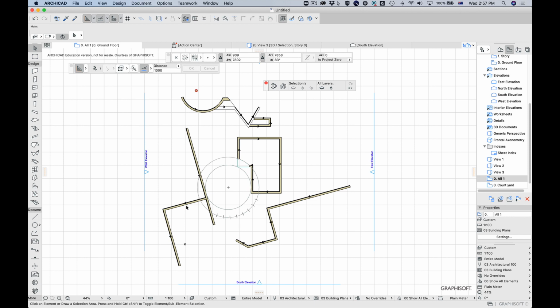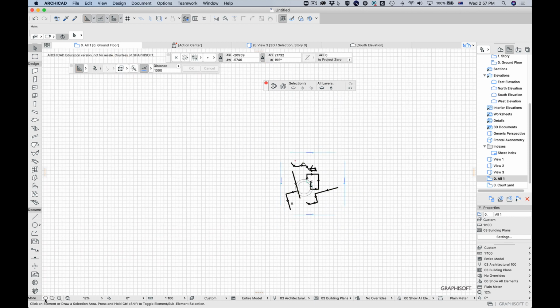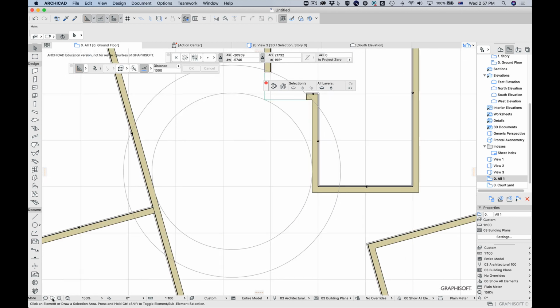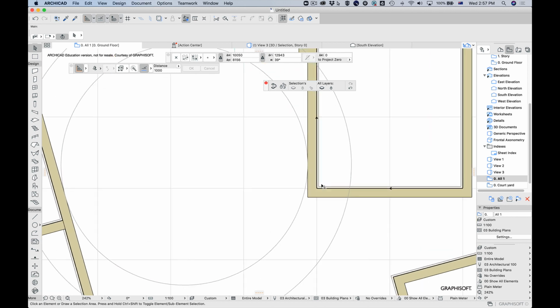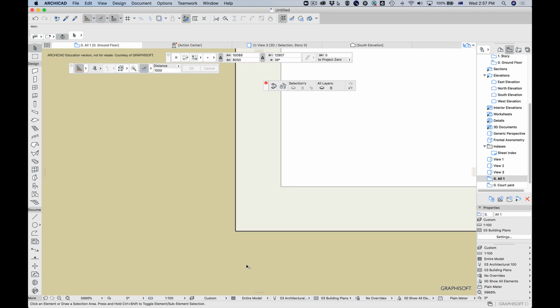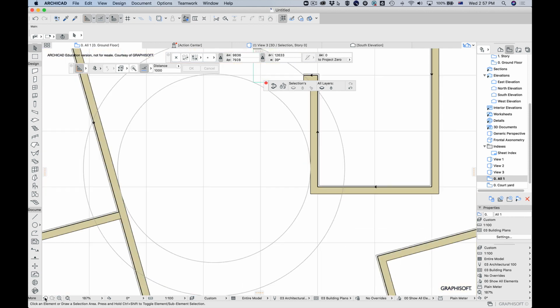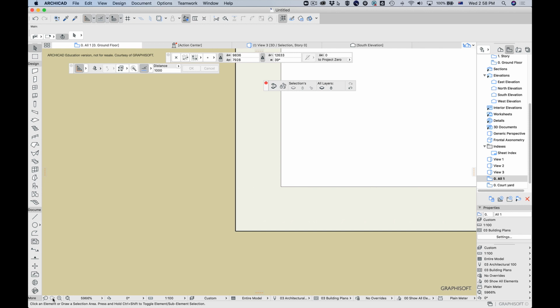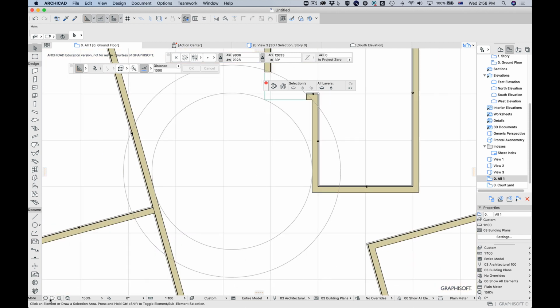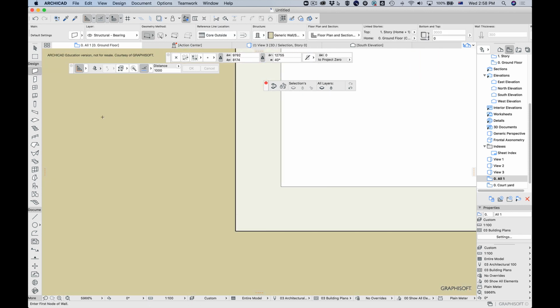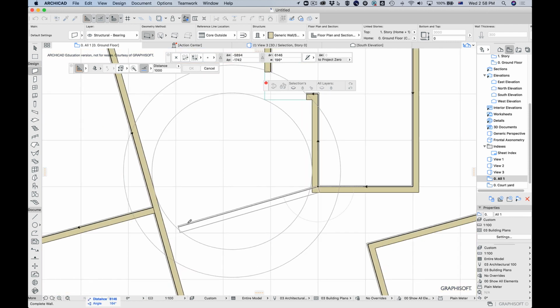While we're talking about these views, down the bottom left corner, this is quite handy as well. This will actually go through all the previous views. So this is really handy, especially when you're working in small areas and you're kind of popping in and out. So I can go and zoom in on the area that I want. So I'm just using the scroll wheel. And then if I want to go back to the previous view, I can click there and then I can go and pop back and forth. And you can even actually, so if I wanted to go and snap a wall so that it touches this point here, I can even do that part way through drawing. Cool.